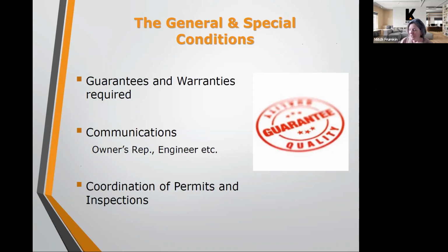For example, again, let's stick with our pavement spec. The condition of pavement changes over time. So we oftentimes will do phased specifications where in 3 consecutive years, different portions of that community are being done. But we recommend that you don't go beyond 3 years because the conditions on that site are changing. So if the work in the specification is based on the current condition of something or the current placement of something, then a generalized spec wouldn't work. But yes, in some cases that absolutely is something you can use.